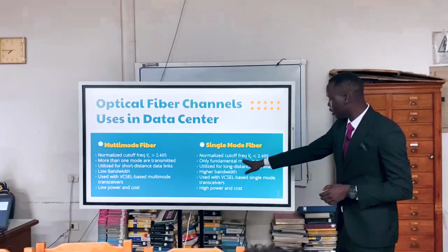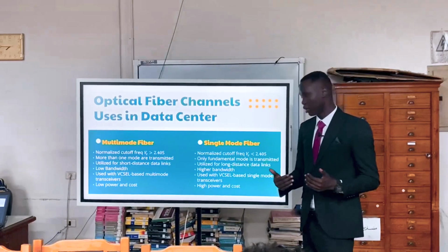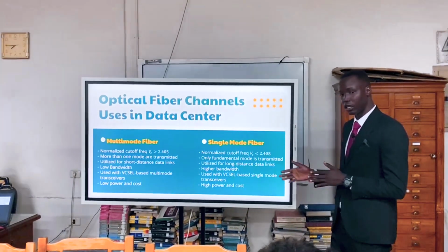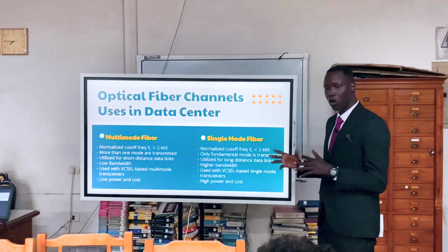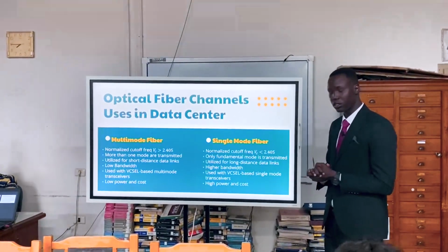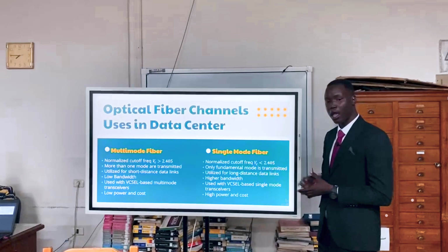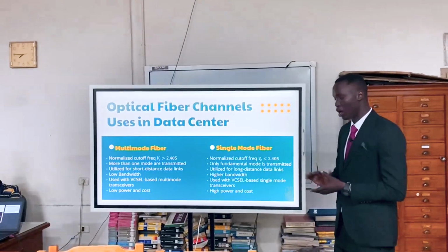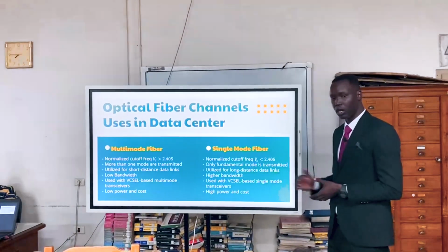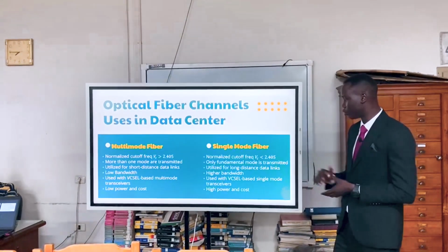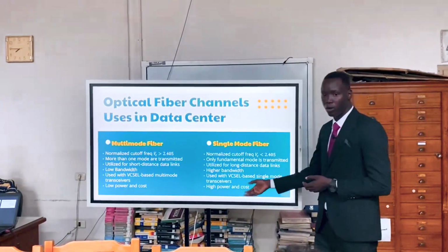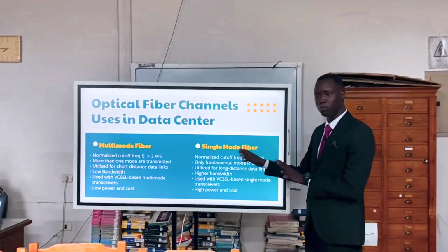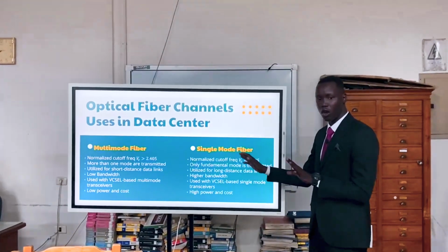In the single mode we only have the fundamental mode, and it is used in long distance data links. We can also utilize it in short distances. It has a higher bandwidth, which is why it has more interest. It uses the same vertical cavity surface emitting laser in the transceiver. It has high power and high cost. And when I talk about the power, I also mean the complexity, the DSP, and all of this part.